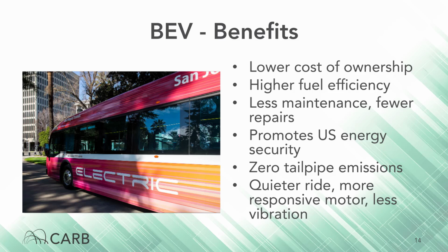This can extend the range of a BEV significantly over the course of a long route or times between charges, and has the additional bonus of significantly reducing the wear and tear on conventional braking systems, resulting in money saved by prolonging brake life. Some manufacturers have reported fully loaded semis storing the full regen energy of descending the Grapevine or Baker grades with no friction or engine braking needed, just the regenerative braking, which has a lot of energy to save for the next portion of the journey.